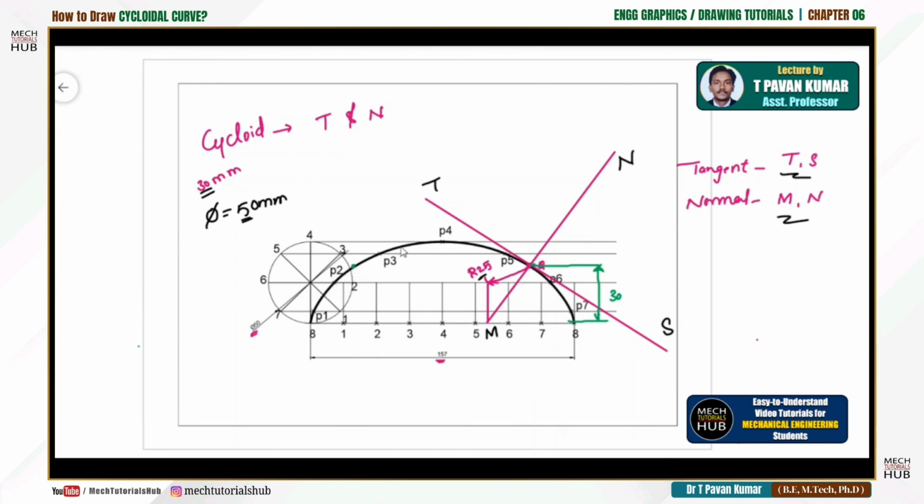If you place it here, then you are going to get the tangent and normal at this particular point. Anything is fine. They may ask you to measure this particular tangent and normal maybe from the directing circle or maybe from the center of the circle. With the help of a compass you can make a mark on the curve. That point acts as Q, followed by whatever radius is given in the question, you have to cut the center. Now here this is C, C1, C2, C3, C4 till C8. This is how we need to draw tangent and normal followed by a cycloidal curve.